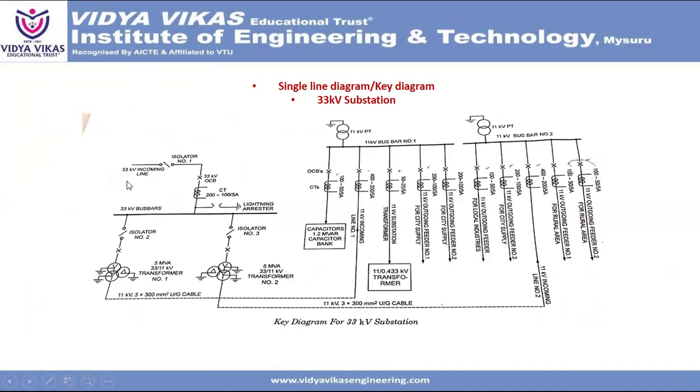Here you can observe the 33 kV incoming line and isolator number one, 33 kV oil circuit breaker, CT and lightning arrestor. Here they are going to use one bus bar, the 33 kV bus bar. From the 33 kV bus bar, they divert the circuit into two circuits, with isolator 2 and isolator 3, and then circuit breakers. This X mark represents a circuit breaker, and then the transformer. This symbolic representation represents primary star, secondary star. Okay, 5 MVA 33/11 kV transformer 1, and 5 MVA 33/11 kV transformer 2.